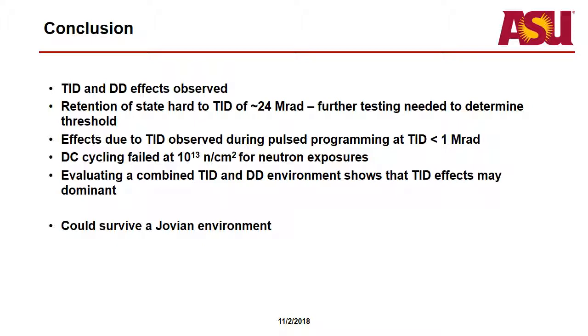So it's not necessarily immune to one or the other. It responds to both environments. Though it would seem, based on the heavy ion tests and the separation of doses between TID and displacement damage, that TID actually seems to be the most relevant or the most damaging radiation environment for these devices.